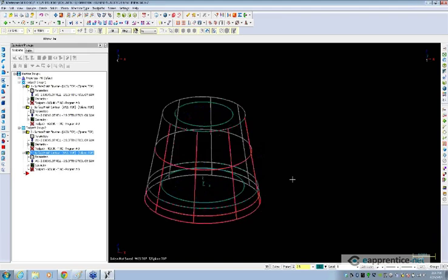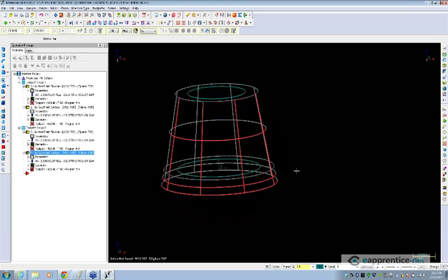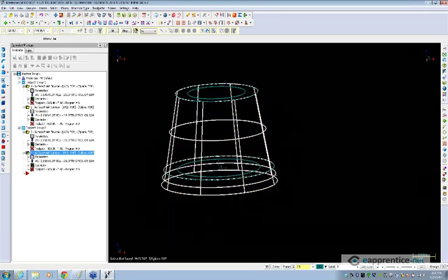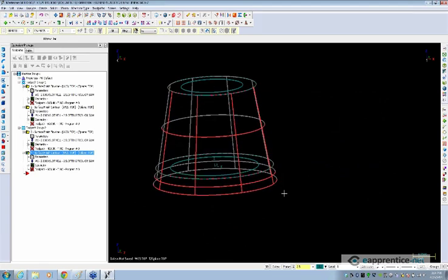So the only exception is going to be when you get into some surfaces that are already trimmed. In those cases, you do end up having to generate separate surfaces in some cases, just depending on the geometry. I could do a whole class on surface manipulation for surface machining. There's a lot that goes into that, but you certainly can extend the surface like I've done here.